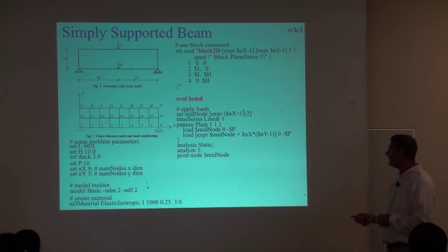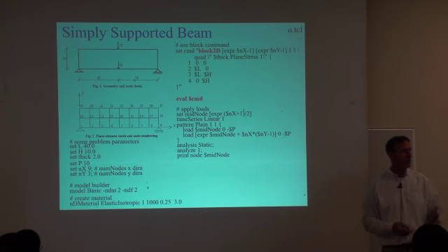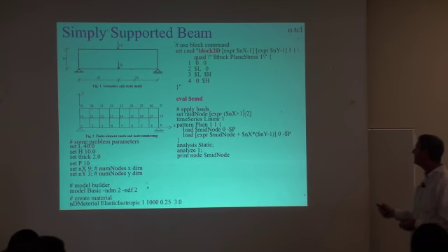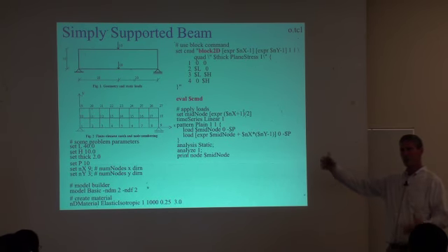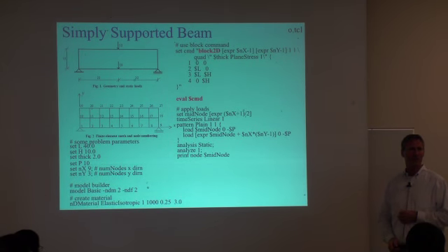So there's another option I could use called the block command. Instead of figuring out where the nodes and elements are, there's a block 2D command. There's also a block 3D command. This command takes the number of X, the number of Y, and where the 2 endpoints are. This point and this point, it automatically creates a mesh with the appropriate elements and materials.